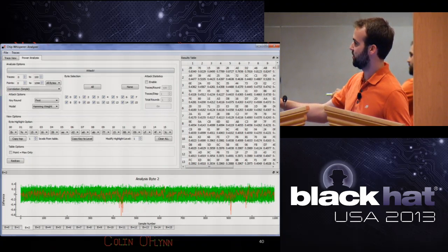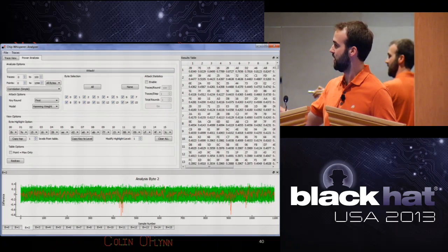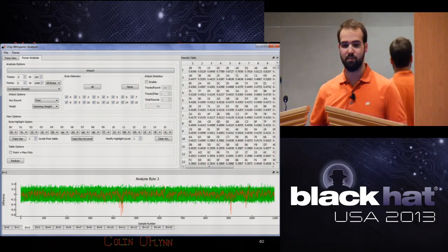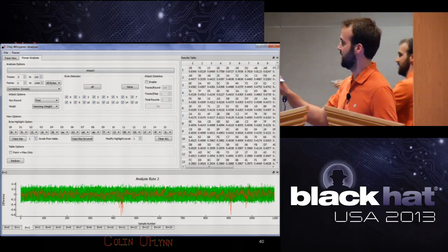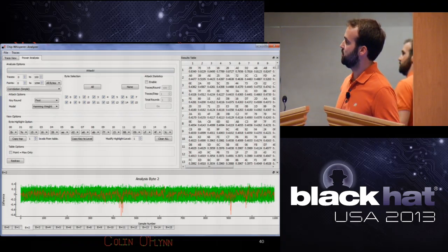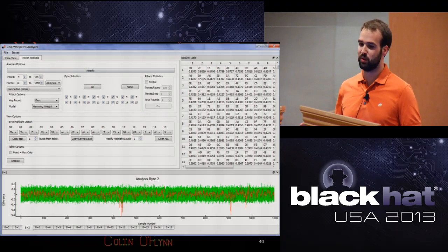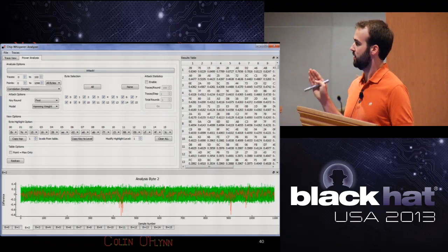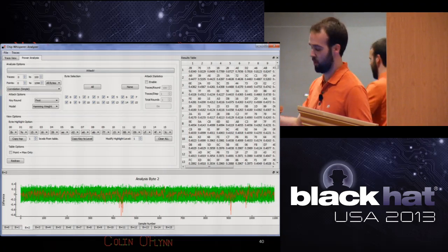So in red, this is the correct key byte, and you can see how we get a bunch of very high matches at some point in time. At this point in time, this is when that step, that S box that I was guessing the system was doing, that's when it's actually doing it. So the other part of this tools, or this whole correlation analysis, is you don't have to know exactly when that encryption or that S box occurred. You can figure it out from the traces.